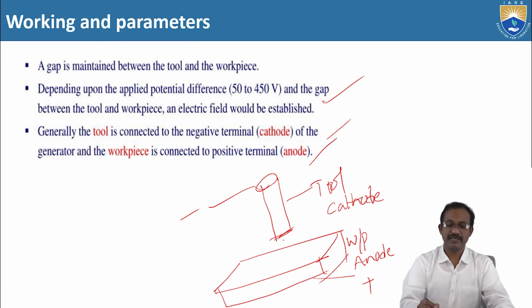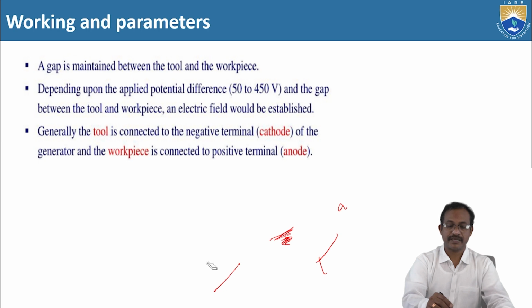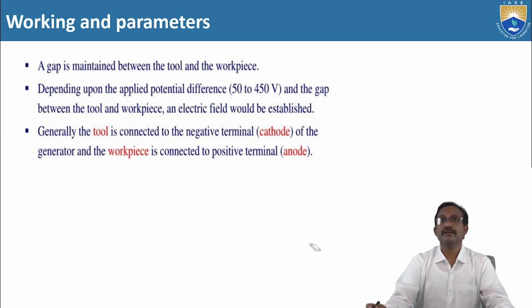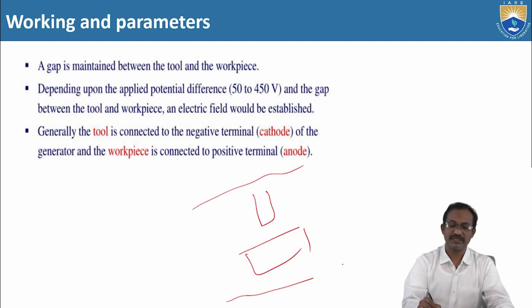Always there must be a gap between the tool and the workpiece to generate the electric field. Next, both the tool and workpiece must be conductors, and the tool and the workpiece must be immersed in the dielectric fluid medium.